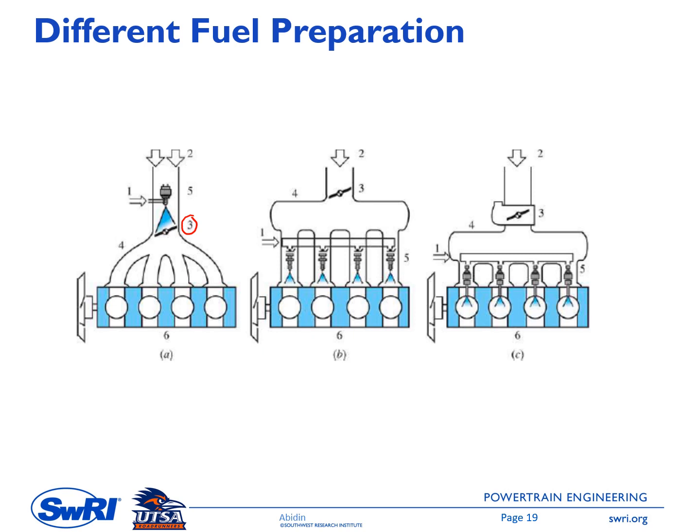And then on the right side, we have one injector for one cylinder, and it is injected at the intake runner. This is the intake manifold, so let me put A here, and this is the intake runner, the passage between the intake manifold and the engine.